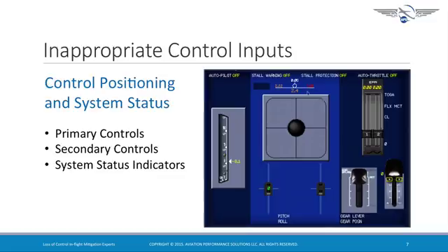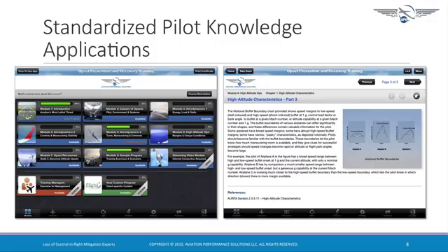And anytime some kind of an exceedance occurs, the instructor operating station, or the area where the instructor is working, is going to flag areas to debrief. In other words, G limit was approached, G limit was exceeded, angle of attack margin of safety was approached, was exceeded, stall, extreme stall, or deep stall, depending on how the operator wants to define those. It is customizable for the particular operator in certain situations.